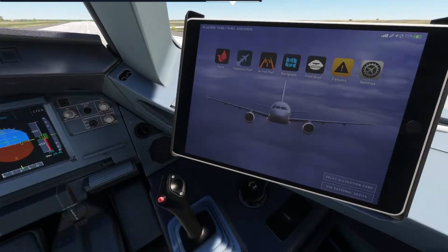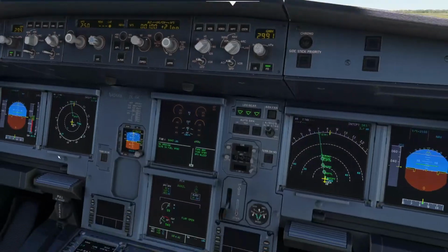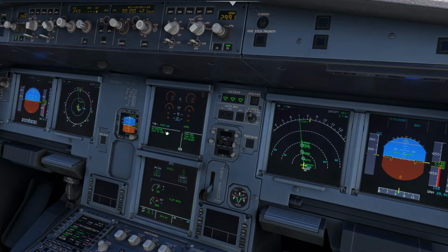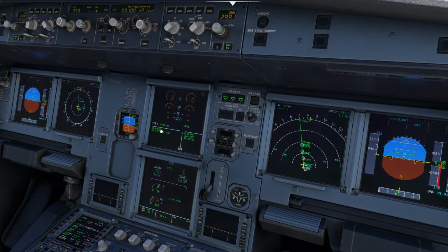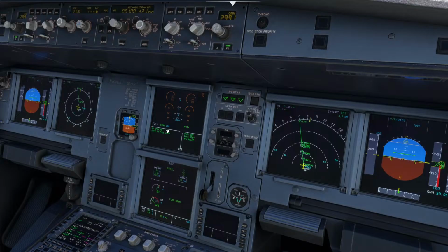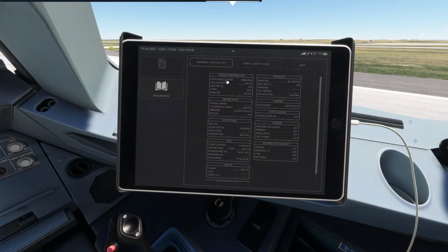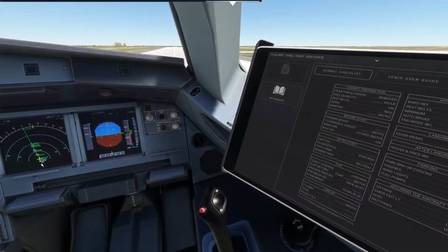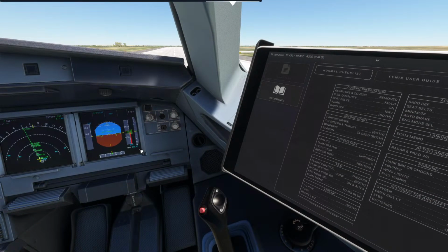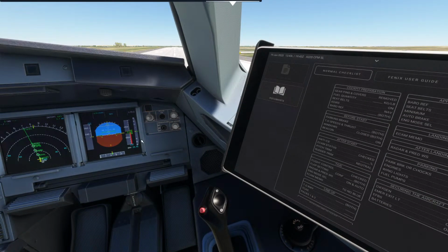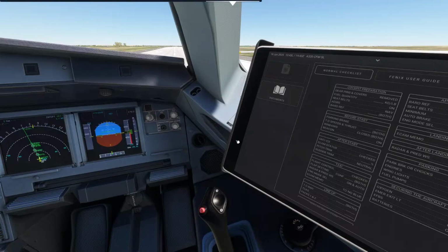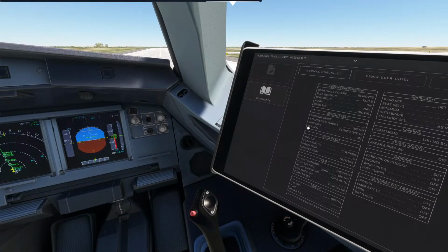We're going to come over here. How much fuel do I have on board here? 6,400 pounds. Yeah, that's enough. It's fine. I could add more, but let's just run the quick checklist here. So cockpit preparation. Altimeters are set. I'm assuming it's 29.01. I could pull up the ATIS, but that looks about right. 5,200 feet.